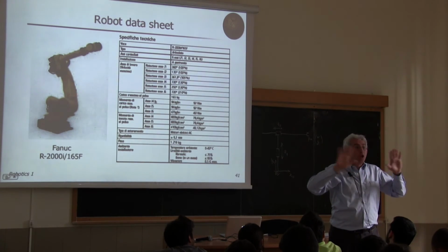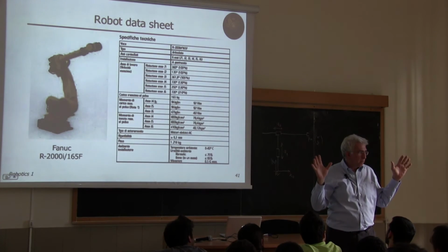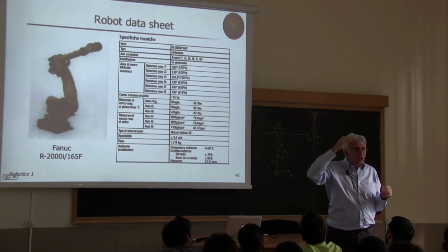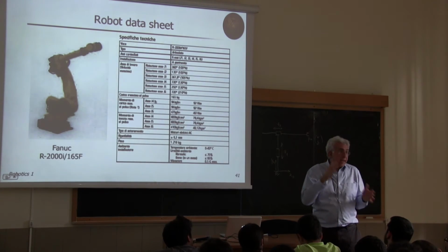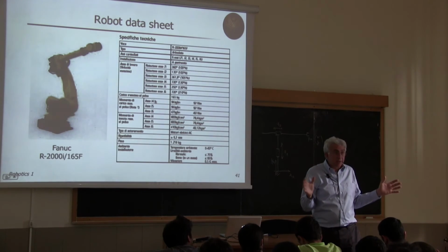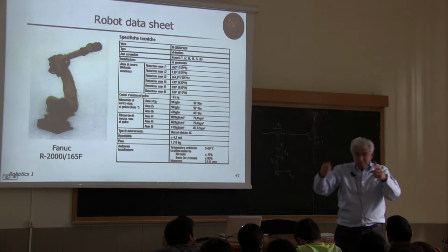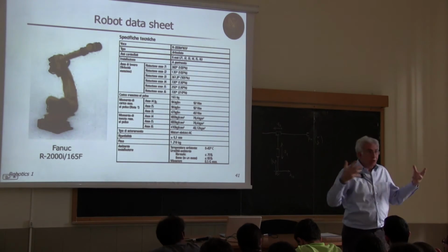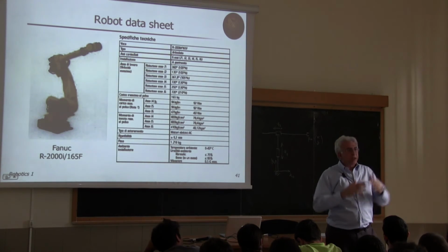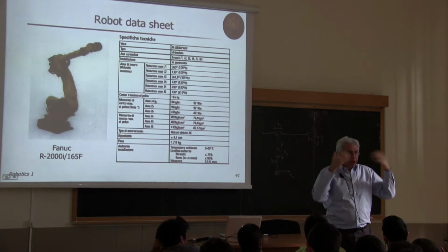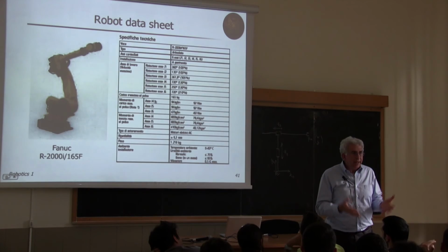Remember that no body in nature is perfectly rigid. This is an ideal model. If you excite with a sufficiently large command or at high frequency, you will excite some vibration in any mechanical device. You have vibration in cars, you have vibration while listening to records or whatever. Okay? So in order to have this first frequency of vibration very high and not excited while moving fast, we need to add mass.